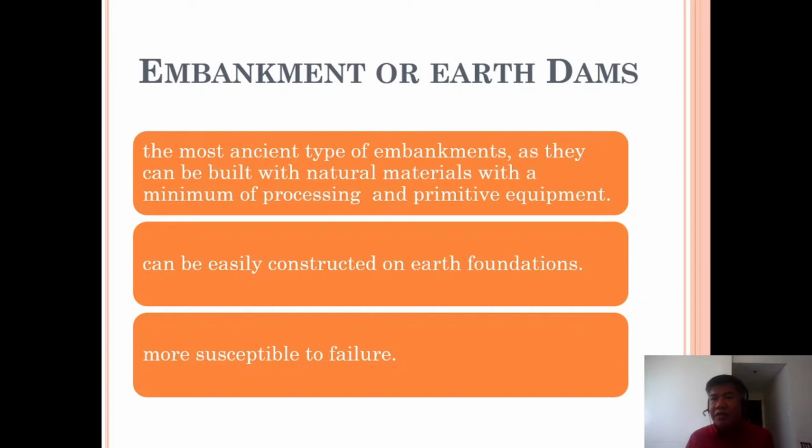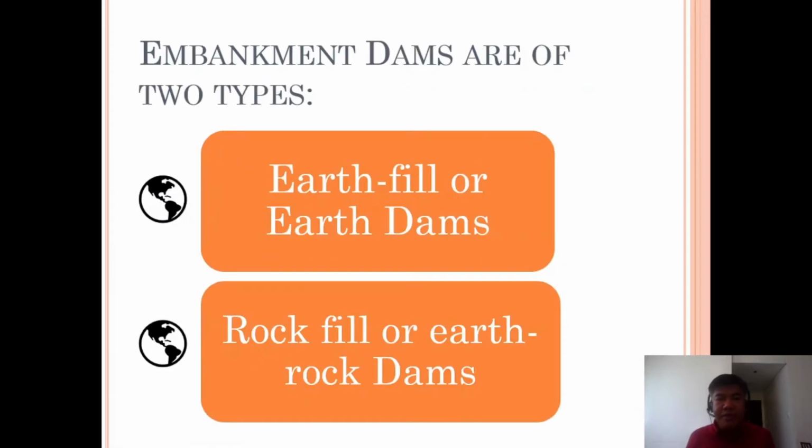Then if it fails, go back again, then redesign or change some of its parameters, mostly the slope if it fails in the slope. For seepage, if it fails, mostly it could be the material type, or you have to add some other measures to strengthen the structure.